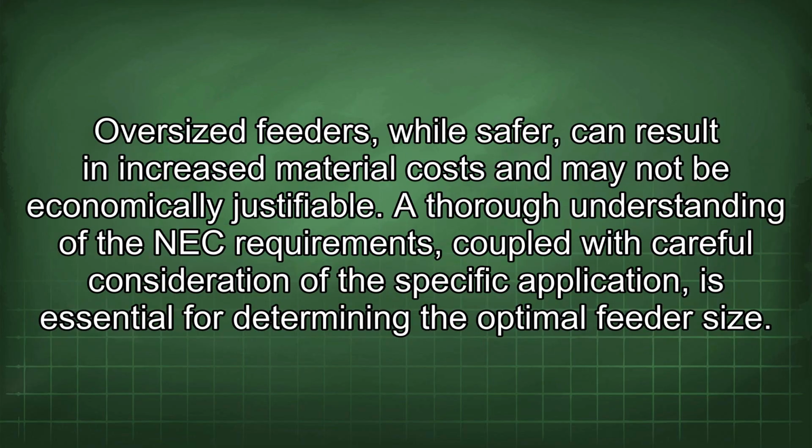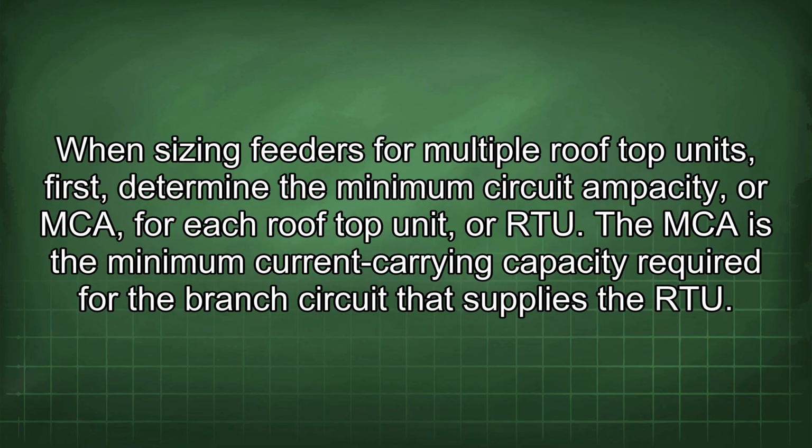Oversized feeders, while safer, can result in increased material costs and may not be economically justifiable. A thorough understanding of the NEC requirements, coupled with careful consideration of the specific application, is essential for determining the optimal feeder size. When sizing feeders for multiple rooftop units, first, determine the minimum circuit ampacity, or MCA, for each